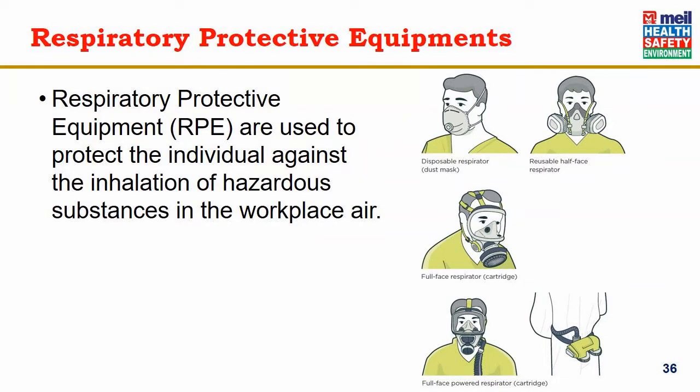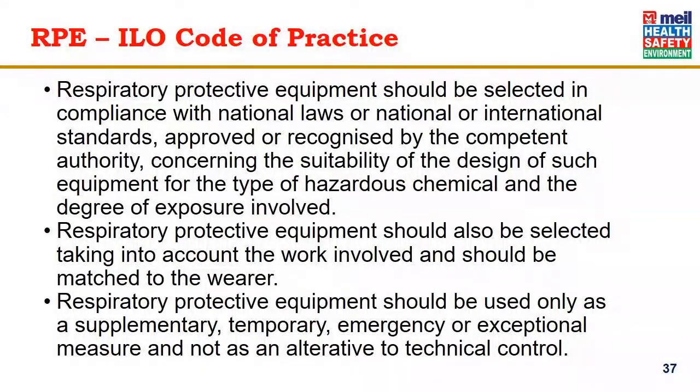Respiratory protective equipment should be selected in compliance with national laws or national or international standards, approved or recognized by the competent authority concerning the suitability of the design of such equipment for the type of hazardous chemical and the degree of exposure involved. So the RPE must be selected based on the kind of hazardous chemical and how much exposure will be involved. Respiratory protective equipment should also be selected taking into account the work involved and should be matched to the wearer. Again, there has to be a proper fit between the equipment and the person. For example, a face mask must be designed to suit the facial contours of the user.